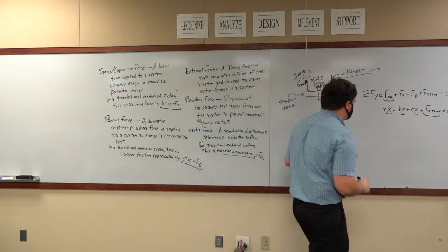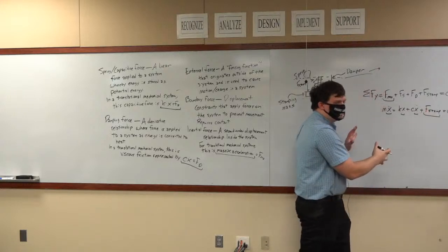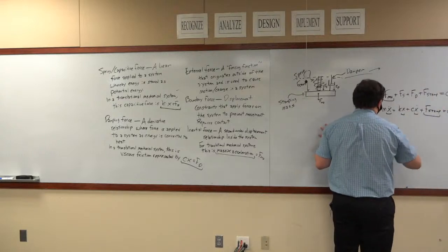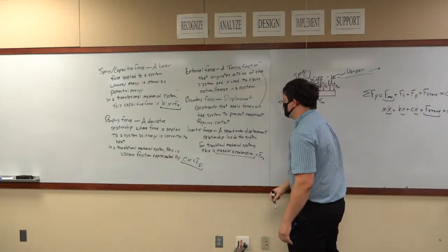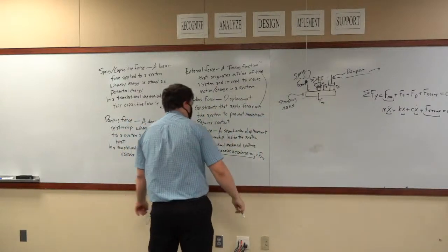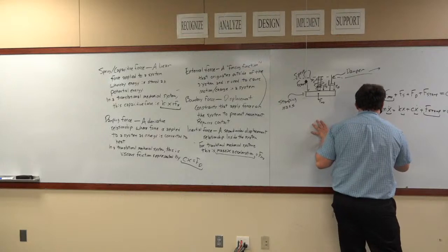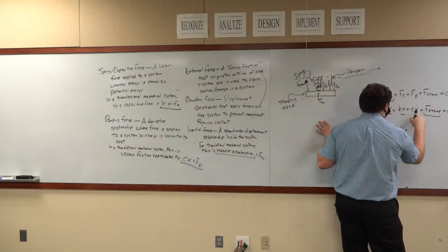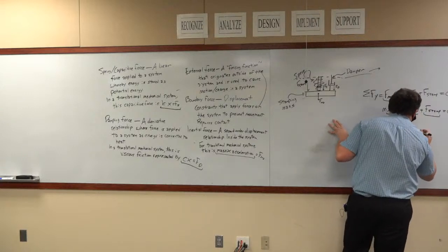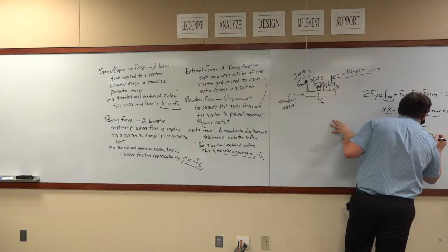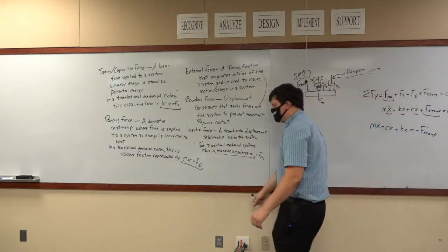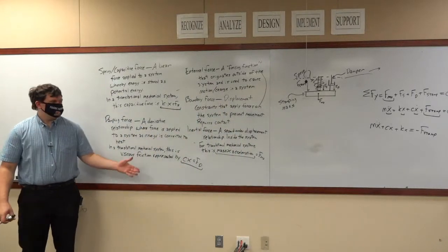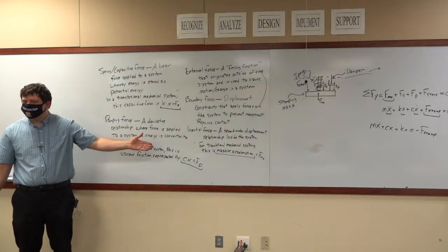So we'll just clean this equation up, take all of our displacement relationships, put them on one side, and put all of our time relationships on the other. Okay, time relationships are these 2, displacement relationships are these 3. Well, you get m x double dot plus c x dot plus k x, yes, I just switched those around, is equal to negative f stamp, which is some time varying equation. Okay? This is the equation of motion for this system.